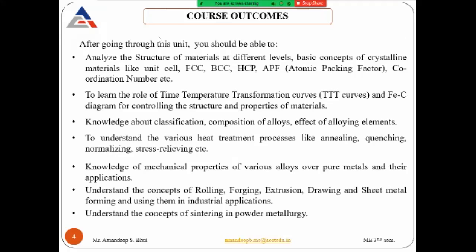Okay, plus you will be able to know about the basic concepts of crystalline materials, like their unit cells. You can see here, you will be able to know the structure of FCC, that is face centered cubic structure. Then BCC, your body centered cubic structure. HCP is your hexagonal close packed structure. Then what is atomic packing factor, what is coordination number. So all these parameters that are related to the material structure, you will be able to learn about.